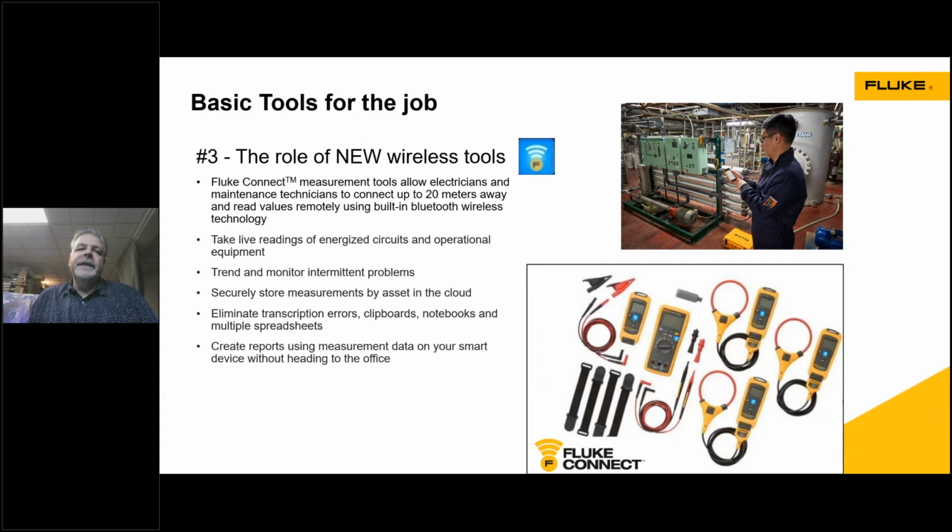So now you can leave the tester inside, for instance, a closed electrical cabinet that'll communicate through that cabinet and be able to read it on your phone remotely. So if you have other load changes or other things you want to investigate while the cabinet's closed, you'll be potentially reducing your PPE and be in a safer environment.